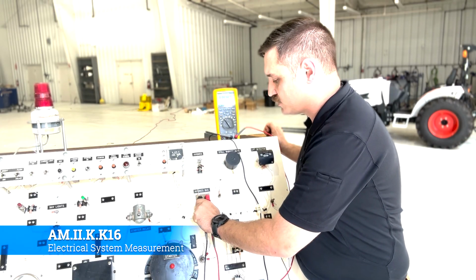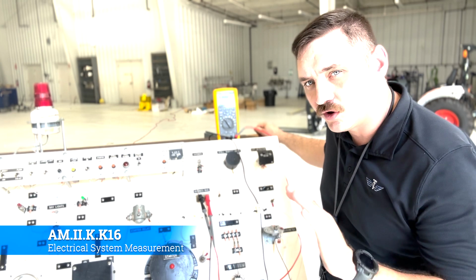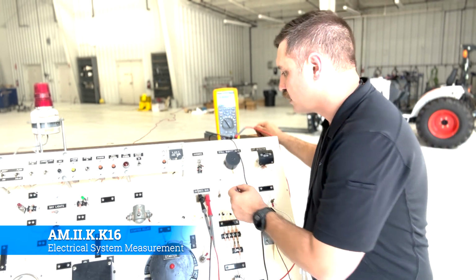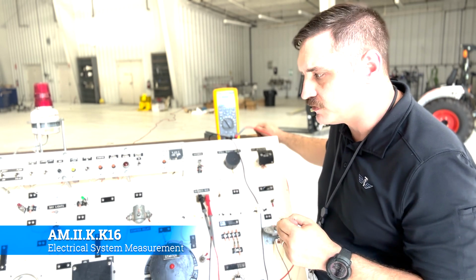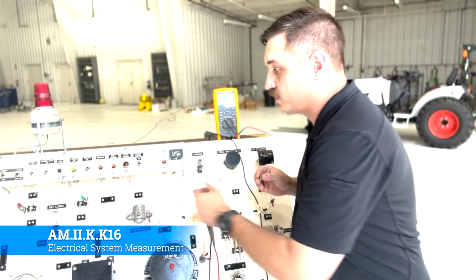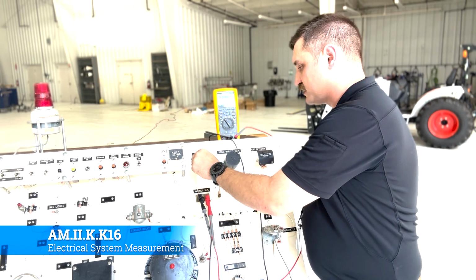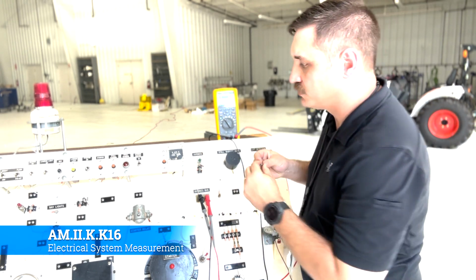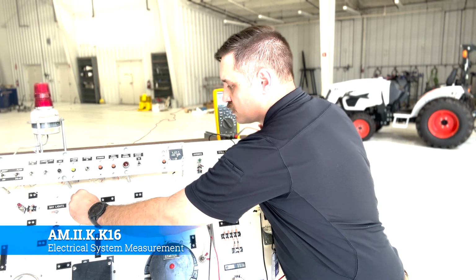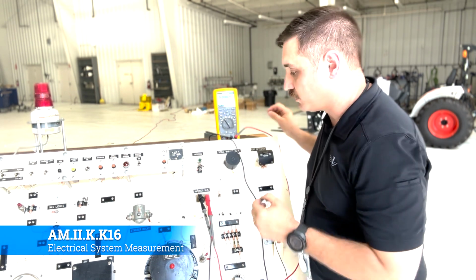Before we get too crazy into it, let's do a bulb swap. Make sure that the bulb isn't the problem. When we pull it out and look at it, we see that the bulb looks like it's good, but we don't know that for sure. But we can see that this little green bulb right here for our nav lights is working. Let's put it on there and see if it's... Okay, so it doesn't work, but let's check this bulb. Okay, that bulb works. So we know the bulb isn't the problem.